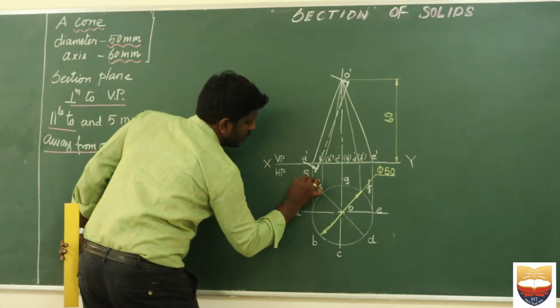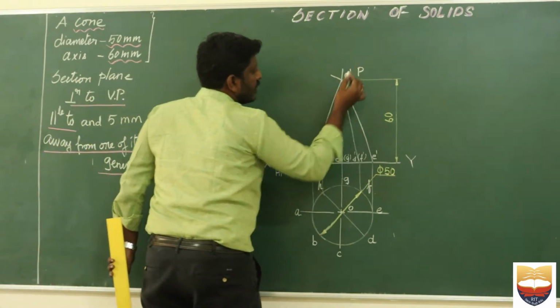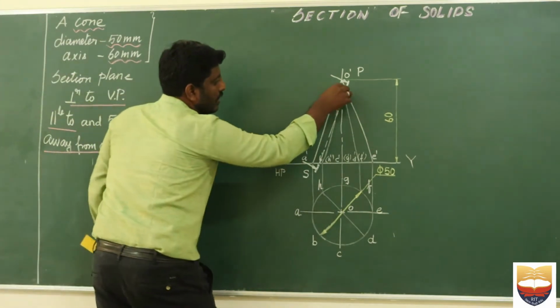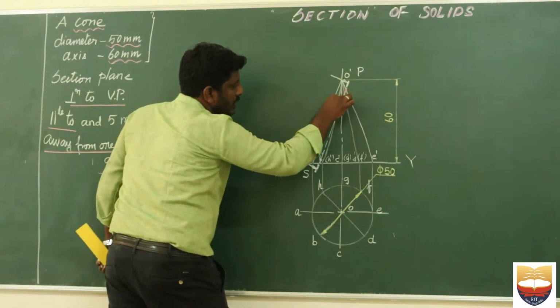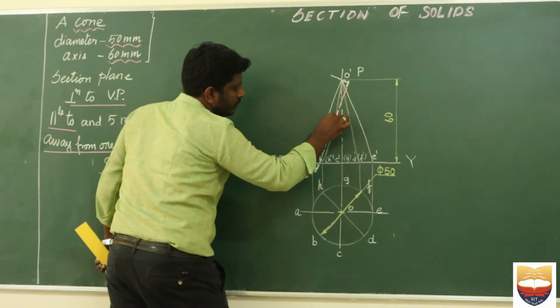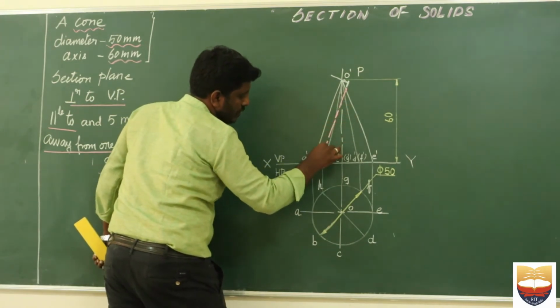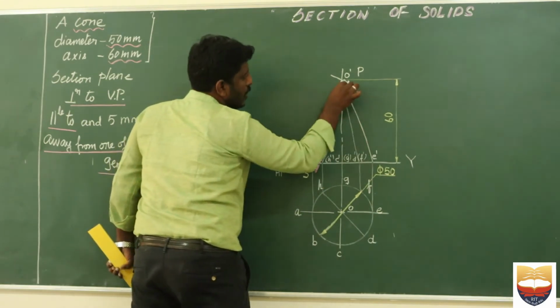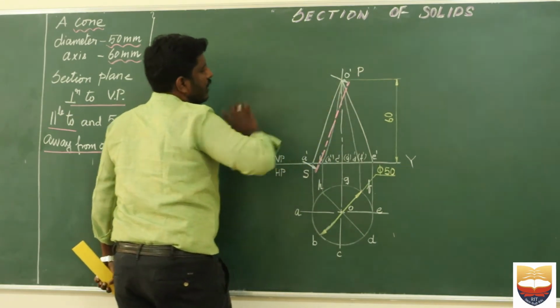It can be named SP. To denote it very clearly, let me draw it with another color. So this is my section plane. It should be dark and thick at the end, and it should contain an arrowhead.